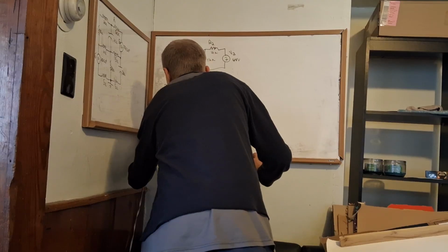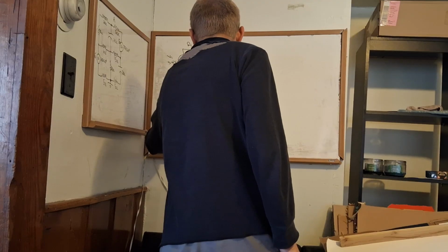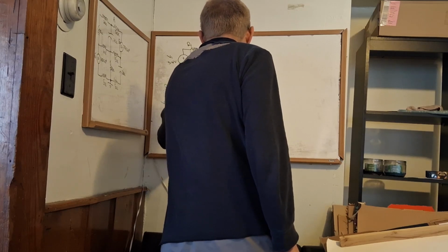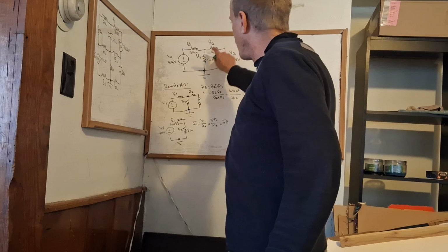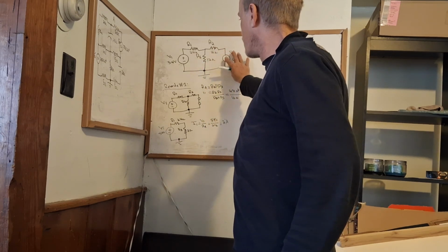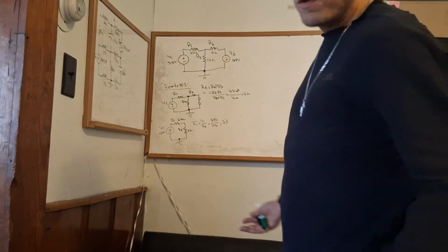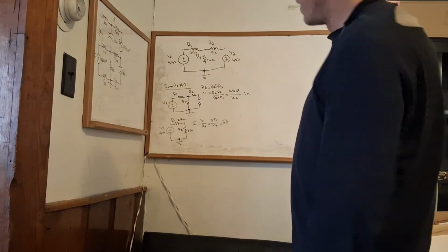Notice you got 27 ohms, you got 54 volts. So the total current would be V1 over R sub A, 54 volts over 27 ohms. That's 2 amps. 2 amps is going through RA. That is not the current that's flowing through both of these resistors right now without this source here. Okay, we got to use the current divider formula here, unless we want to solve for the voltage first and then do all that. No, you just go straight to the current divider formula.